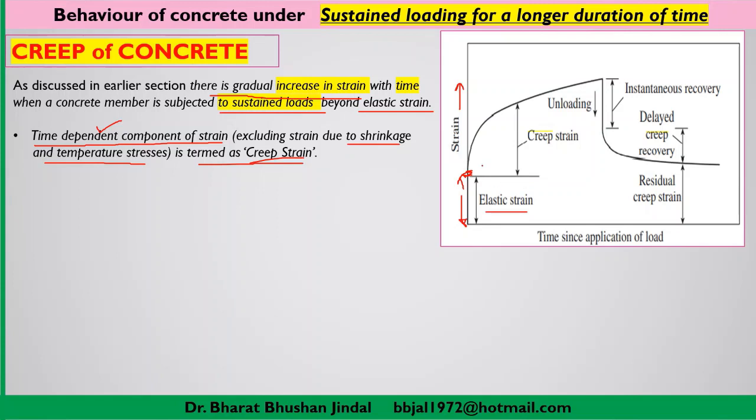Now you can see that beyond this particular point, the graph is like a parabola, a curved shape. Beyond the elastic strain, the strain which you observe is known as creep strain, and that is due to the creep behavior. After that, the graph will reach somewhere here.